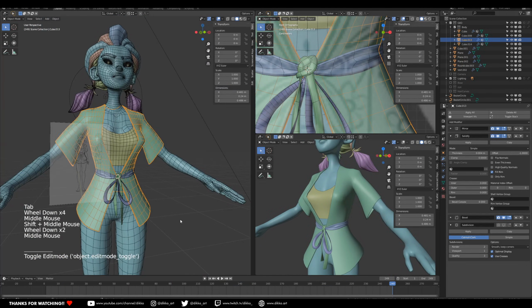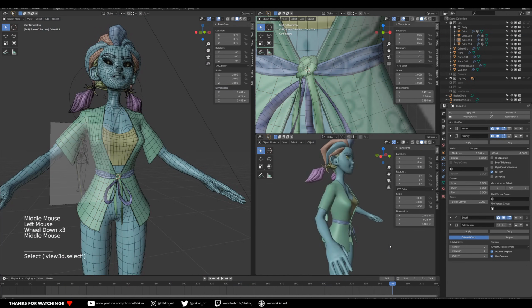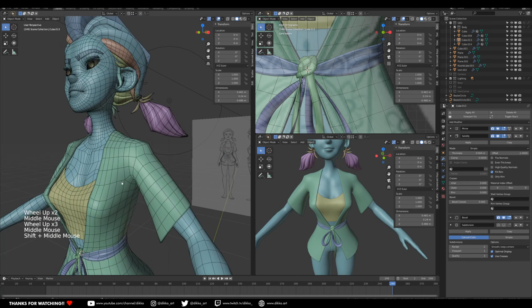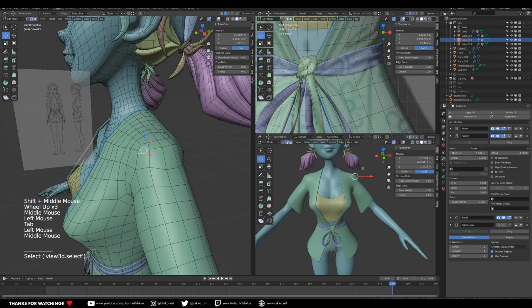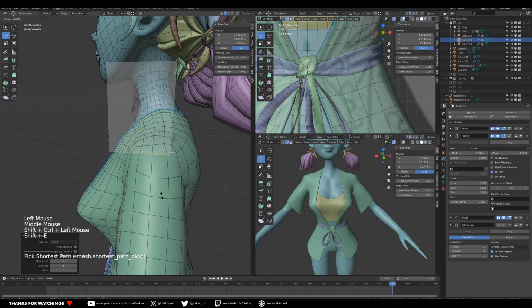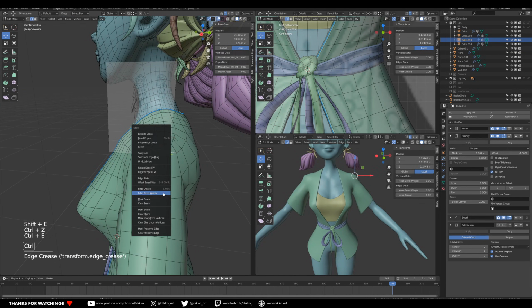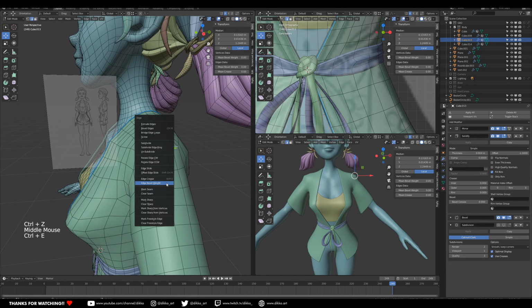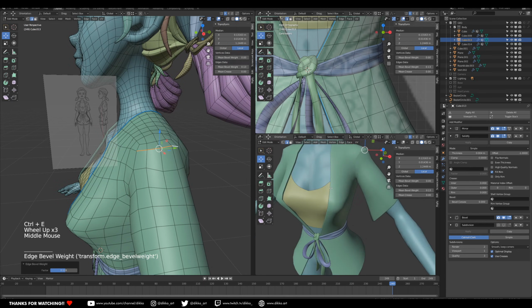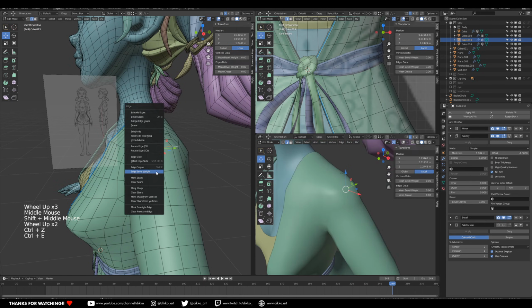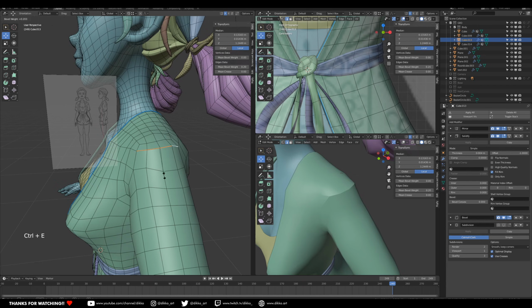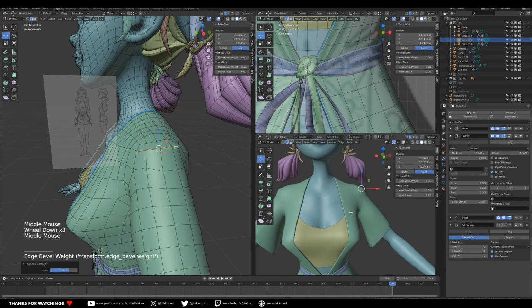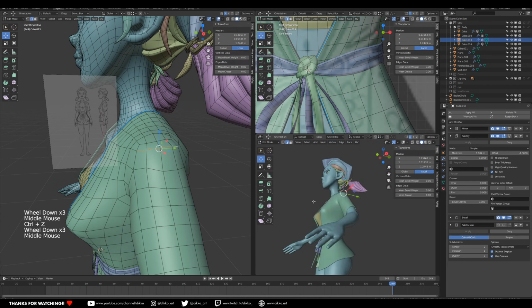Now, if I had made this character with a ridiculous scale and then had to bring it back into a realistic scale and then apply the scale, all the modifiers would mess up. Suddenly that 5 millimeter thick coat would be 5 centimeters. So it would be going absolutely crazy. It would look like you completely messed up the model, when in actual fact, the modifier had just been adjusted for the scale. So again, while you're modeling, be aware of those kinds of things. Otherwise, you're going to run into a world of problems.